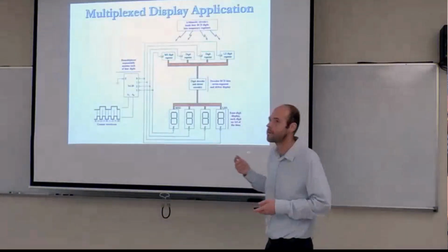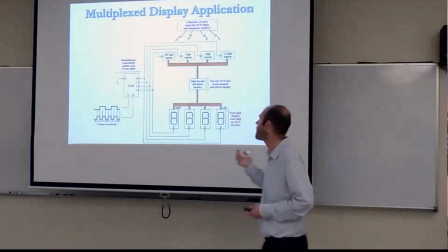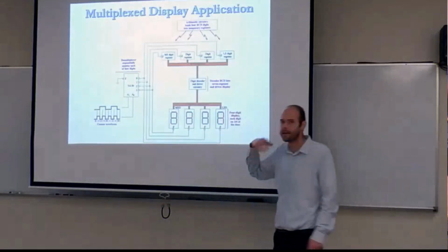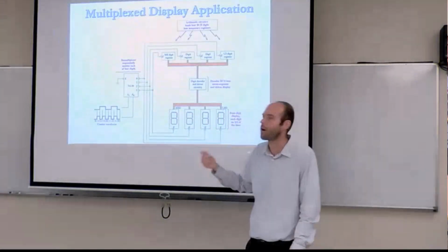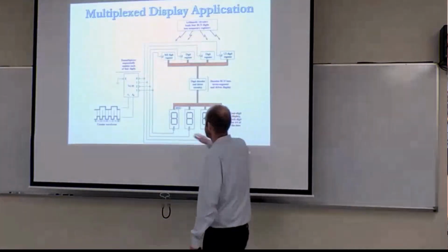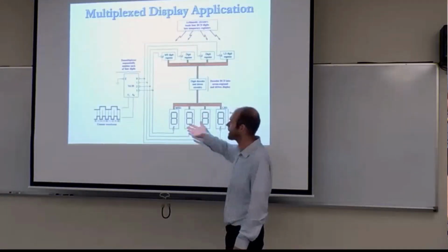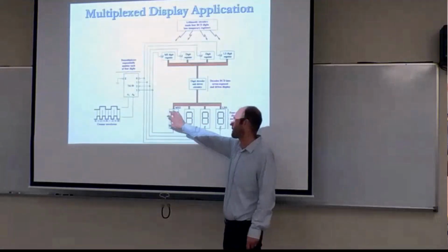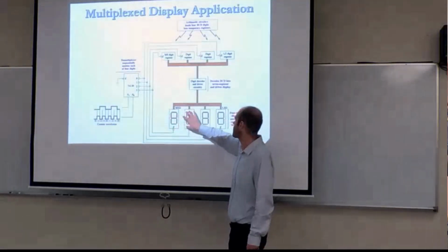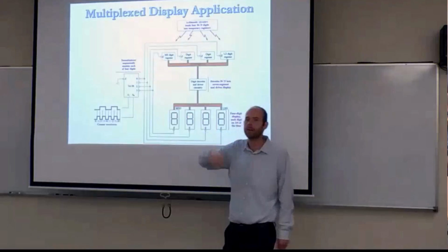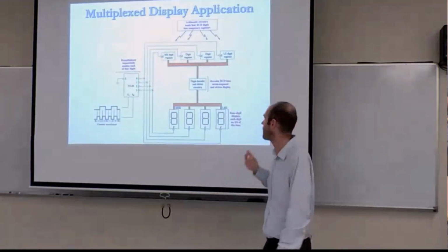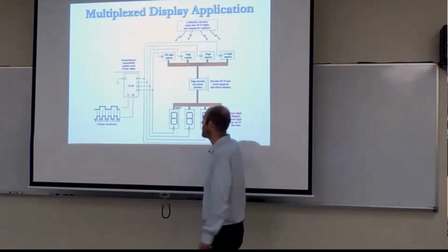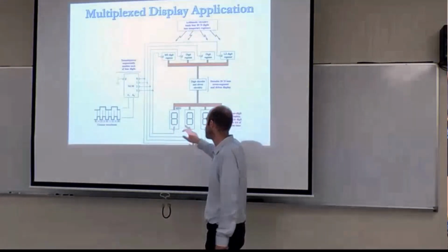So why introduce multiplexing right now? Well, 7-segment displays use a lot of multiplexing because they can take advantage of how slow our eyes and brains react to changing LEDs. With 7-segment displays, you could wire the 4 data channels and enable to each display, but what is more commonly done to save space is you'll have one data bus going to every light, and then each light will also have just a single enable.